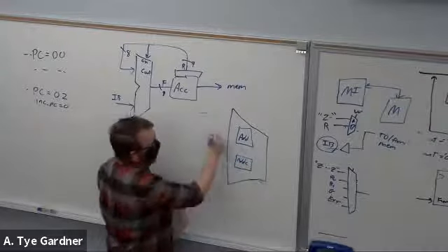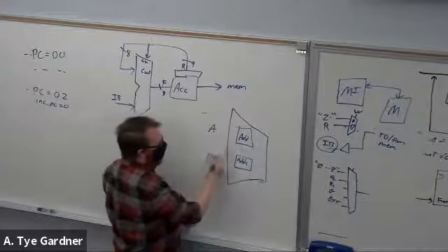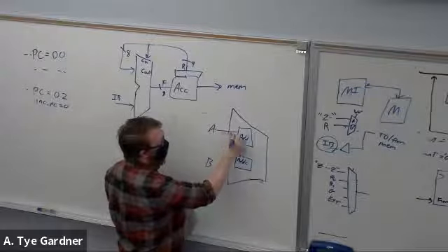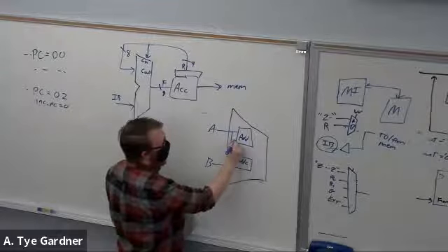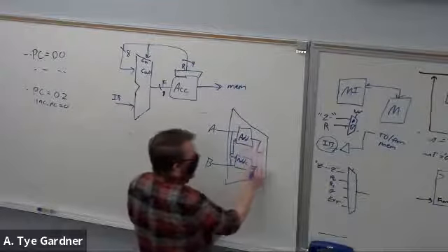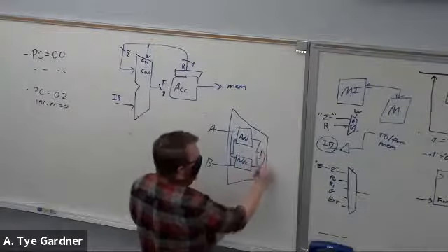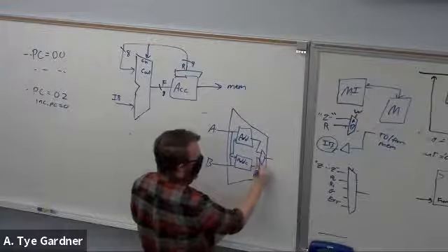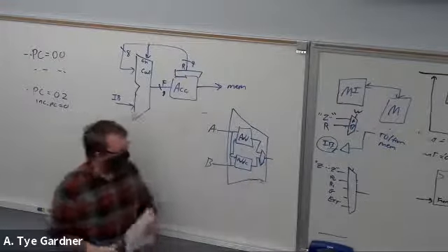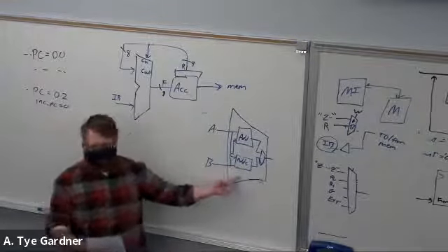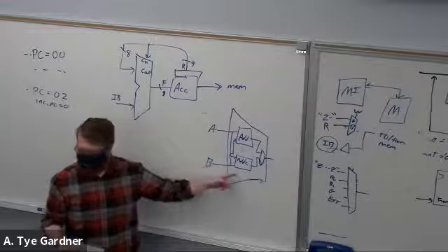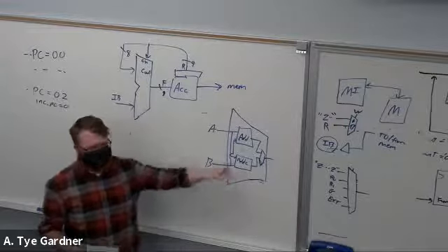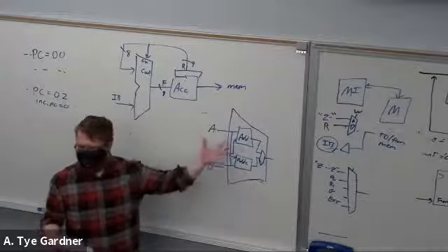What a lot of students will do is they'll be like, well, there's an A and a B input, and then they come into the mux, and then they get mapped like this, and then there's an output, and then, oh yeah, here's another mux or something, right? And you try and shoehorn the components into the mux. A mux is nothing more than a when else statement. As soon as you start putting other logic into the mux, it stops being a mux and starts being an ALU.